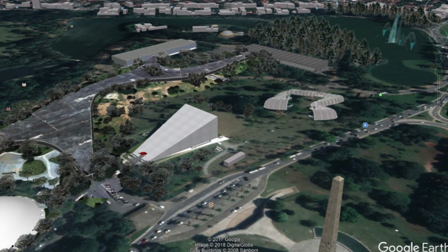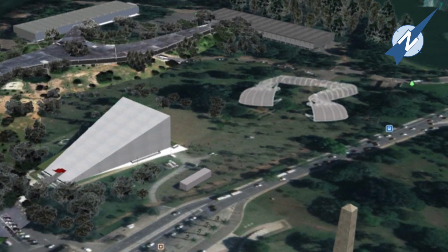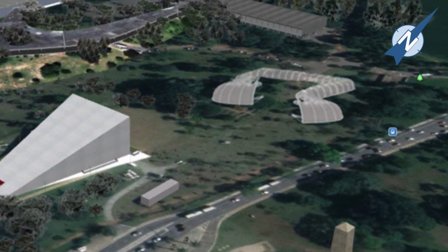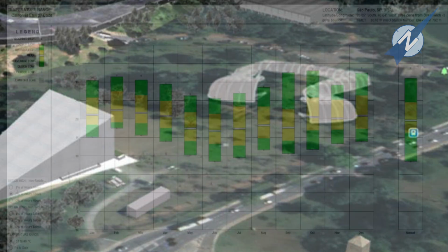The orientation of our project can be illustrated as shown. After conducting solar analysis of the summer and winter sun, it illustrates the solar pattern and the way the pavilion casts and creates shadow. The open part of the pavilion is located towards the south, and the closed part faces north, protecting its inside from the frequent wind that usually blows from northwest towards southeast.